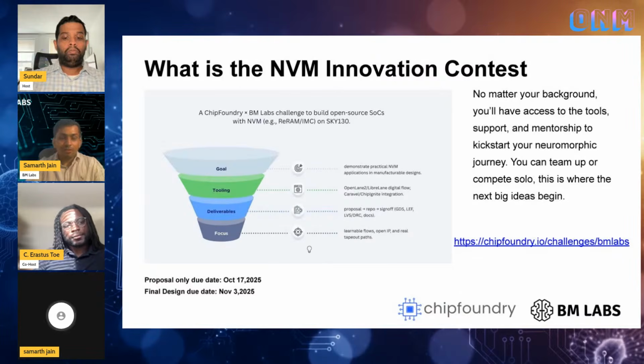Use the C program, which I just showed you with the Caravel, like an Arduino C program. Check at the behavior level whether it's working fine. Use OpenLane to finally submit it to the factory, right? So it's very easy if you are a digital designer. It might be a little tricky if you want to do it in the analog domain, right? That's why we provide a digital interface to our IP, so that it's very easy for a first-time beginner to use these IPs, because the digital flow is very much automated right now.